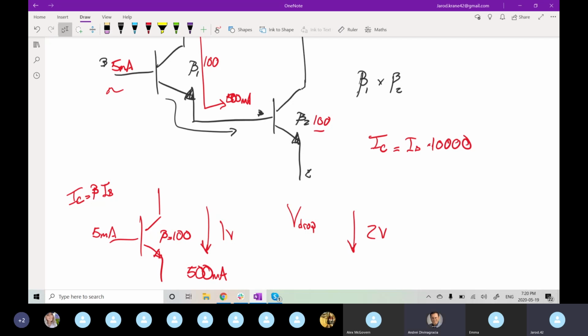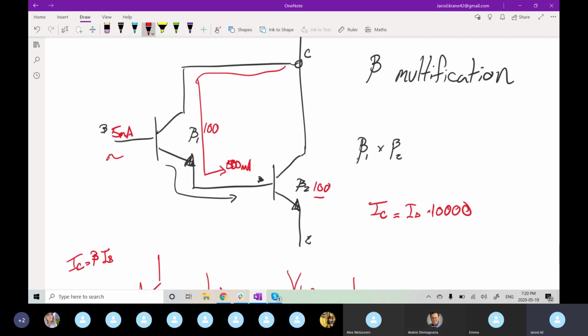So in transistor-based bucks, I'm sure the internals would have a Darlington pair to allow for the high current drop. But it's more typical in LDOs and linear regulators compared to bucks.